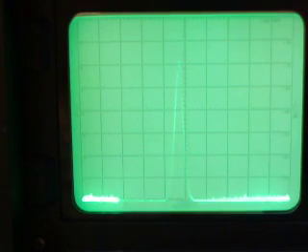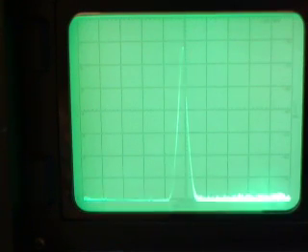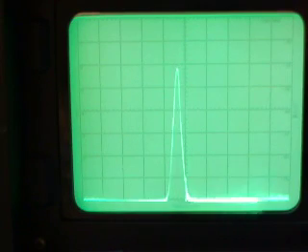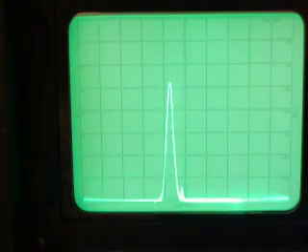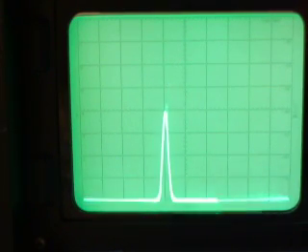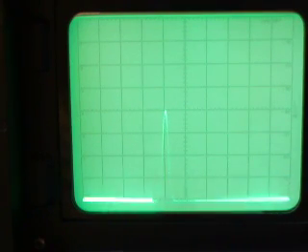around here somewhere, kind of there, where we're at 9.9976 megahertz, when we've dropped down to around about here, we're already at least 20 dB, if not more, further down, attenuation going on here. Now remember that 6 dB is half voltage, so that's more like 26 dB.